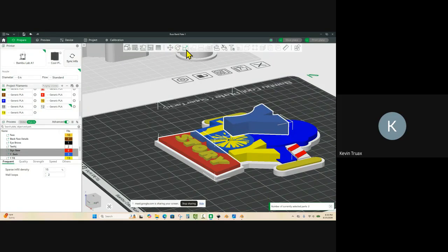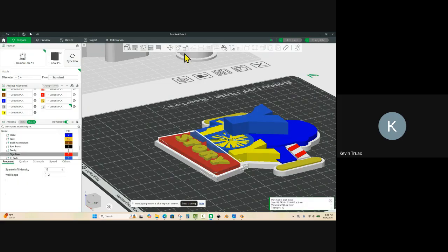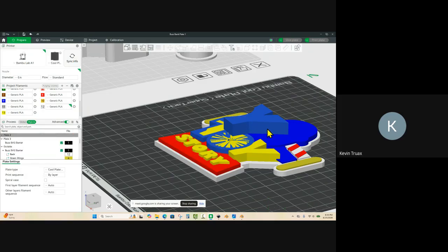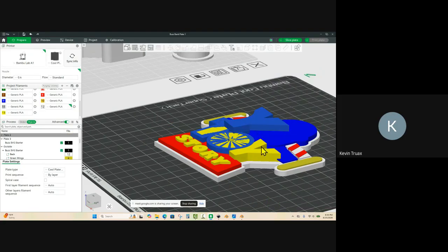How thick is that? So we need just this red piece. I forgot how thick we made that. Let's look. We made that 3. Okay. So then I want this to be 5. I want this piece to be 5. So let's go ahead and make it 5. Okay. And then we'll go ahead and use the assembly tool to put it on that white plate.